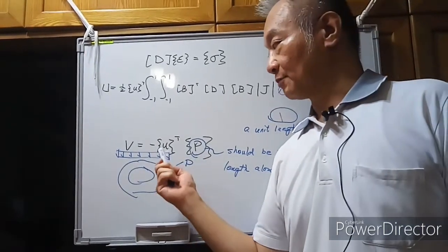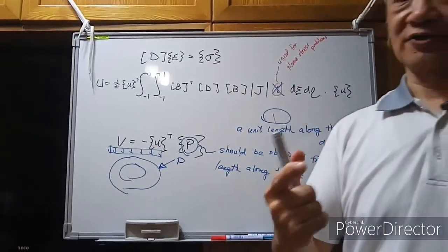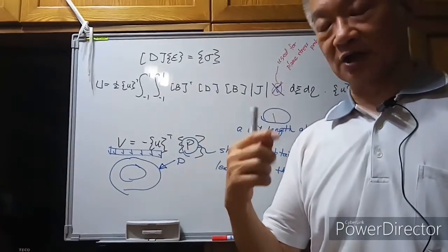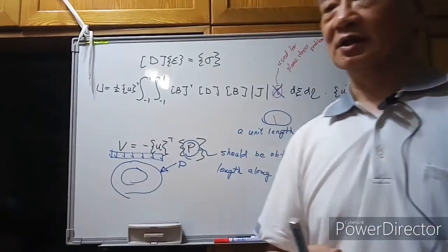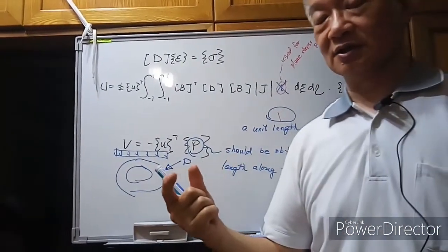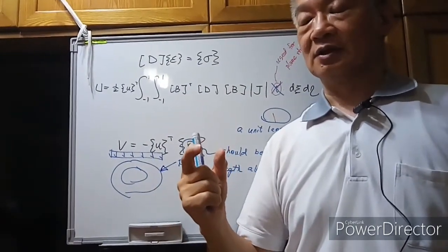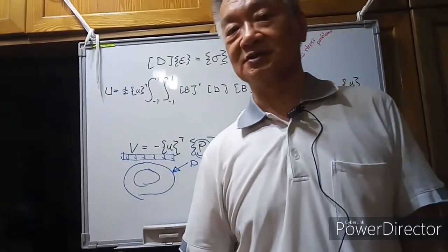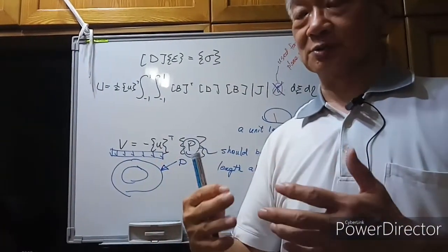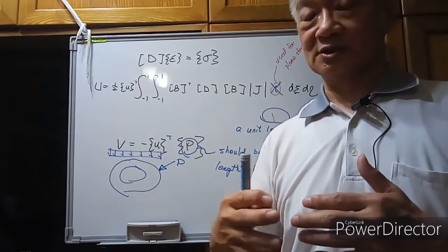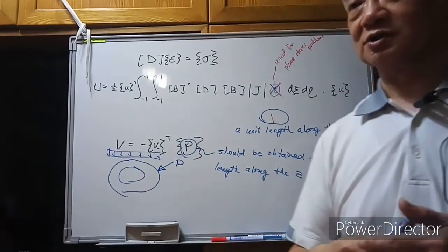But for the plane strain problems, you can output 4 non-zero stress, including sigma z, and also you can output the 3 non-zero strains. Okay, so for this model, I will not repeat the procedure since almost all the procedure is the same as the plane stress problems.